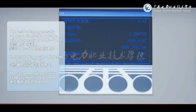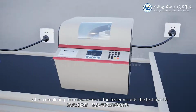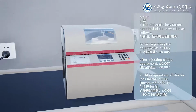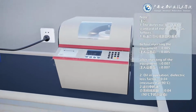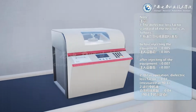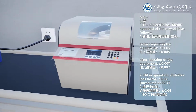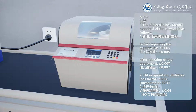The test voltage generally adopts a sinusoidal voltage of 40 Hz to 60 Hz, with the size depending on the test liquid, and the recommended electric field strength is 1 kV/mm. After completing the measurement, the tester records the test results. Note: 1. The dielectric loss factor standard of the new oil is as follows: before injecting into the equipment, less than or equal to 0.005; after injecting into the equipment, less than or equal to 0.0072. Oil in operation, dielectric loss factor, less than or equal to 0.04, measured at 90 degrees Celsius.